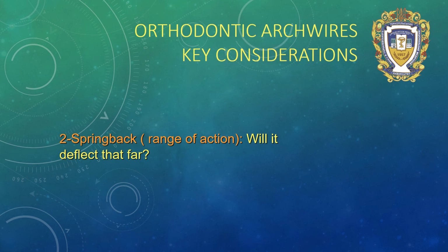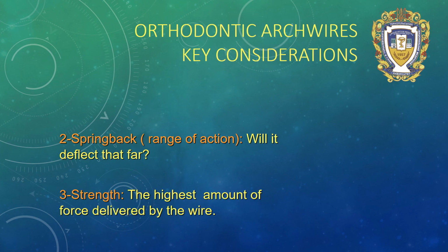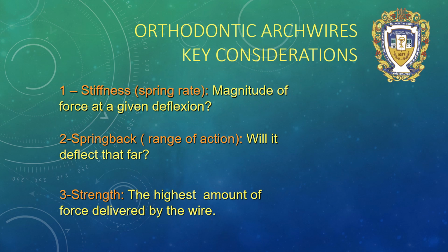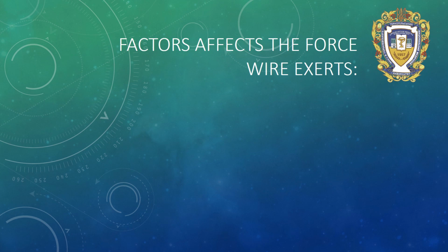What about spring back, range of action? Will it deflect that far? Third point, strength: the highest amount of force delivered by the wire. And stiffness: it is spring rate, the magnitude of force at a given deflection. Factors that affect the force the wire exerts: